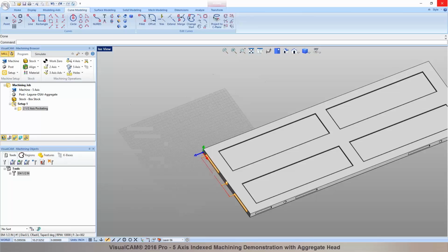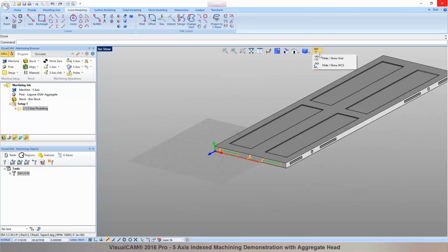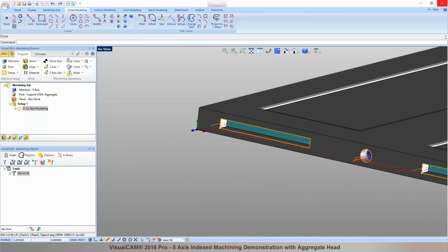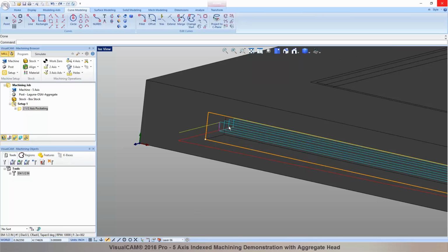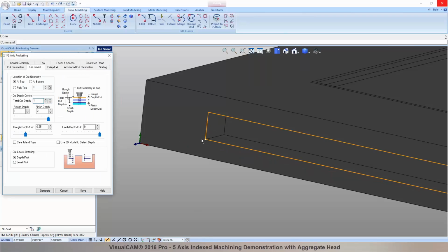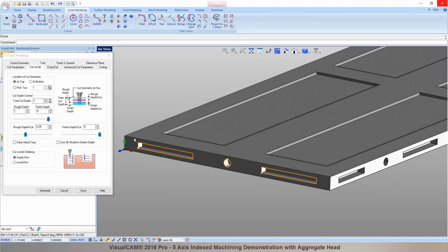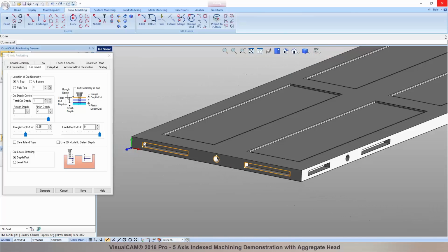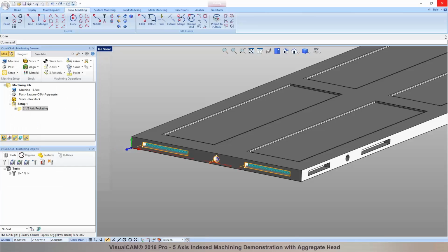Interesting. So can you pick the depth of that pocket just by clicking the faces? That's often what I find myself doing. I believe you were running the plugin in Geomagic Design, right? Yeah, correct. In the standalone system, rather than picking faces, you can actually just snap to an endpoint or a near point on an edge. Okay, so that's a standalone system feature. You can snap to an edge or an endpoint or a near point using all of these object snaps that you can find right down below in the status bar. So I just snapped to the 2 endpoints. Okay? So we got this side program.